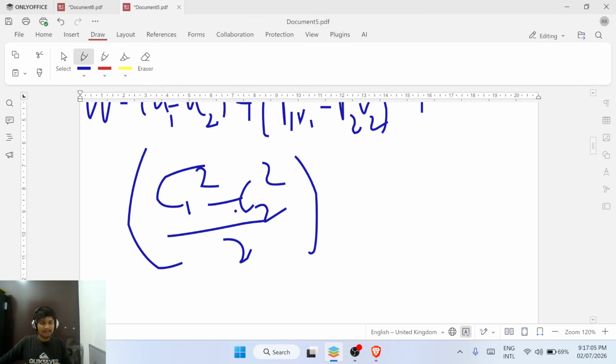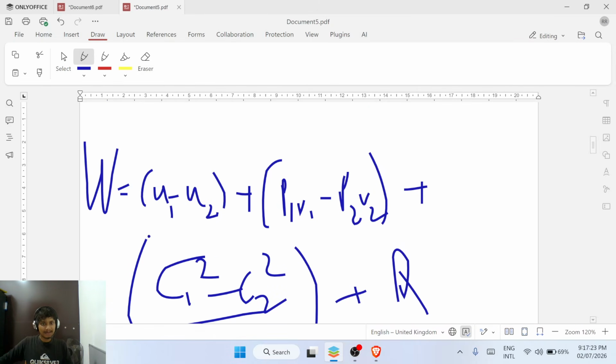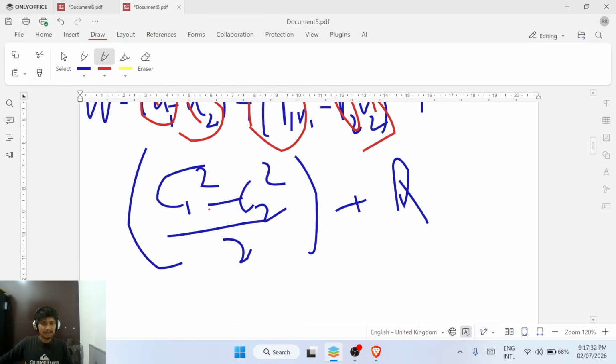If you write it down anywhere, you will quickly understand. If you just watch the video, you may get confused about what this is. If you want to understand, please write it. So W is equal to U1 minus U2 plus P1 V1 minus P2 V2 plus C1 square minus C2 square by 2 plus Q. Now we have to substitute everything. We know U1, U2, P1, V1, P2, V2, C1, C2, Q. We know everything.